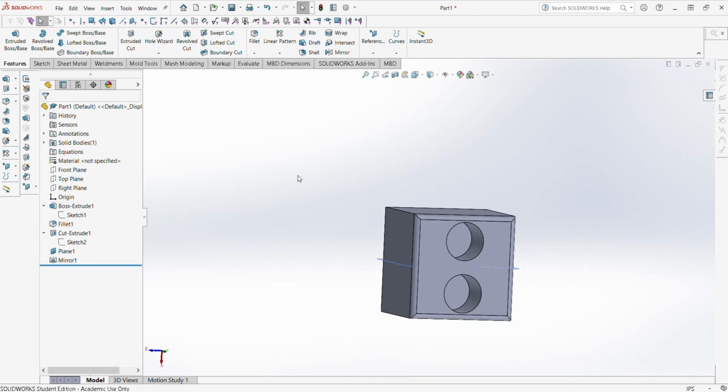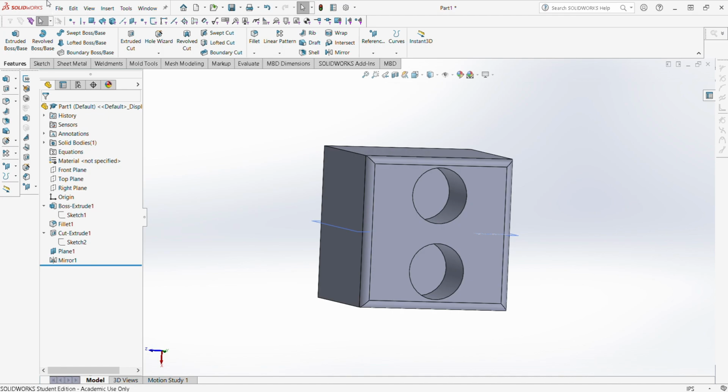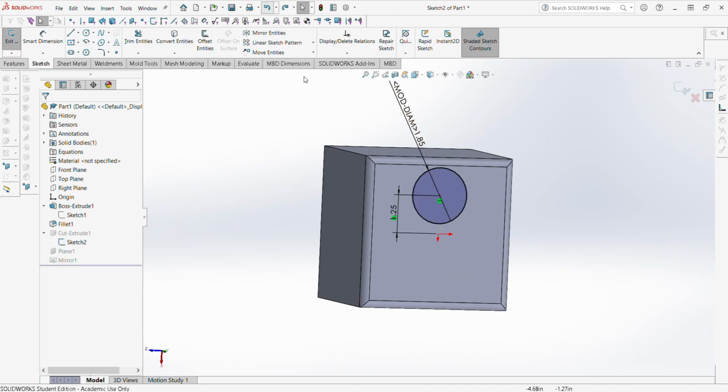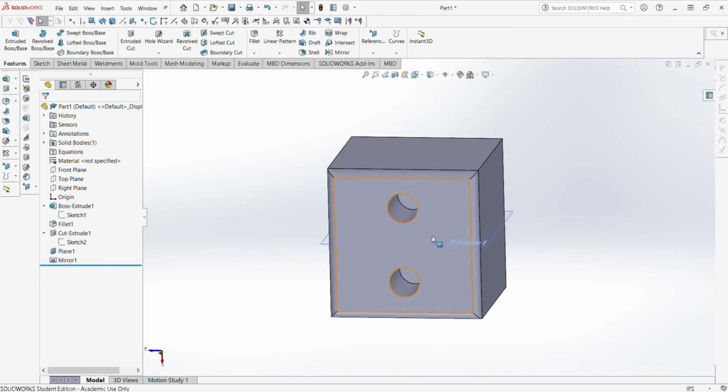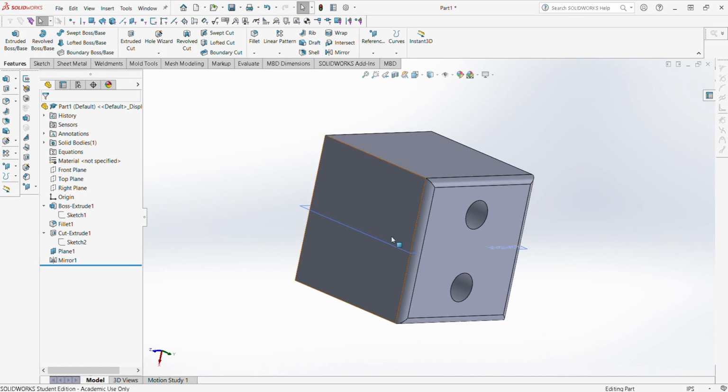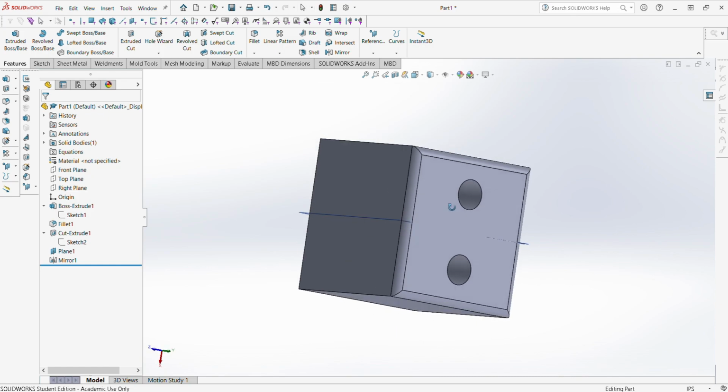So if you need things to be independent from each other, oh, this is also your best friend, undo button. So if you need things to be independent from each other, don't mirror them, because, well, I'm not sure how to break them away from each other once you've mirrored them. I don't think you can. So just know it's handy to do, but just make sure they don't need to run independent from each other.